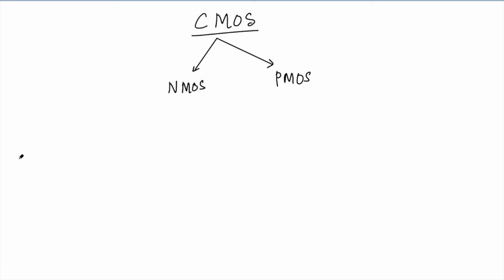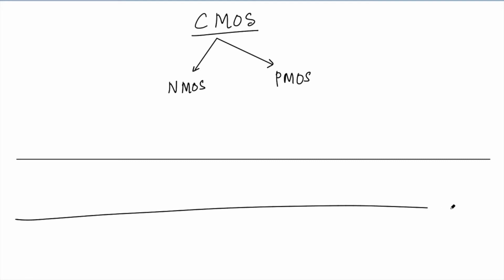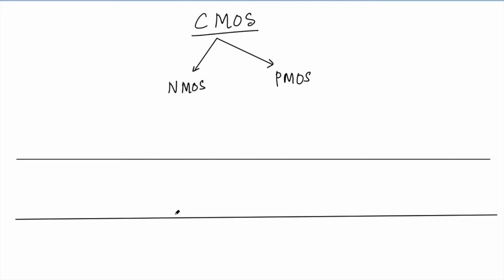So in a CMOS technology, I have this P-type substrate. This is basically the die, the IC, right? P-type substrate. And of course we can easily make our NMOS device. So I'll have my bulk P plus, and I'll have my N plus, and my N plus. And of course I have my oxide here.